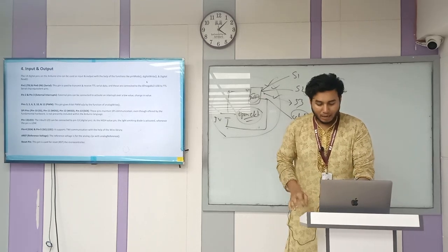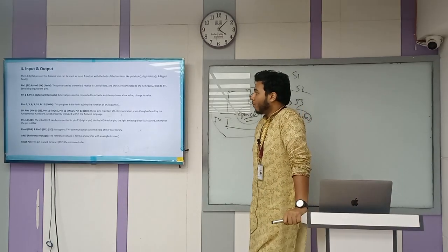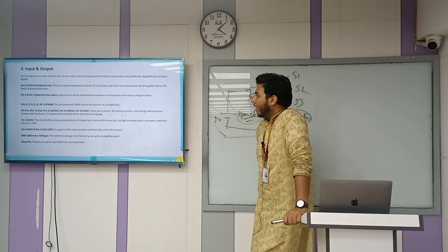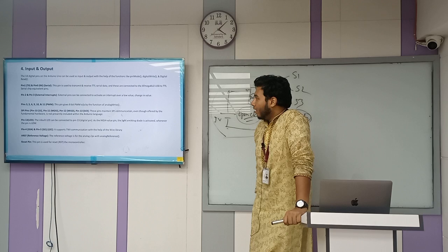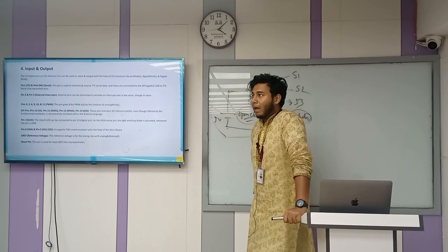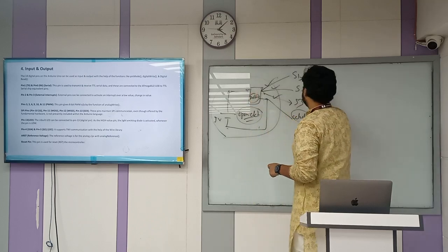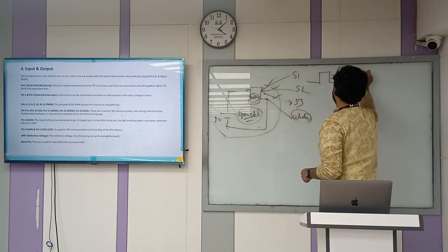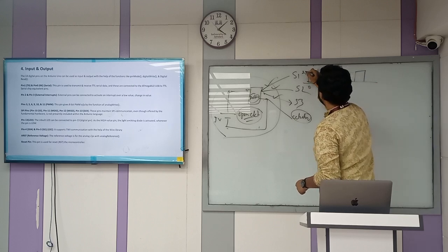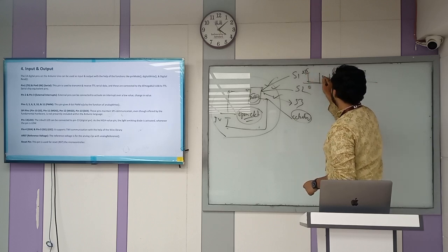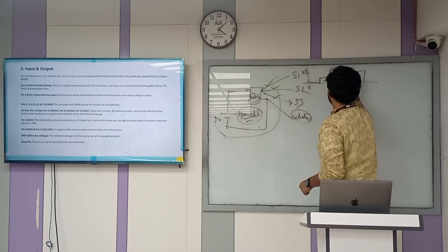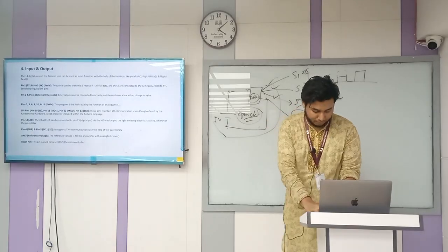Then I have talked about the special pins like pulse width modulation pins, PWM pins, and these pin numbers are 3, 5, 6, 9, 10, 11. So what's the basic benefit of these pins? I've already talked about the cycles, the duty cycle. So you have a range of 0 to 255. These cycles indicate the range of the operations with the help of the converter.